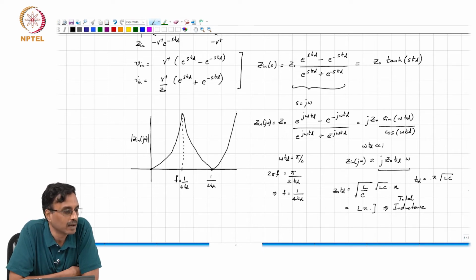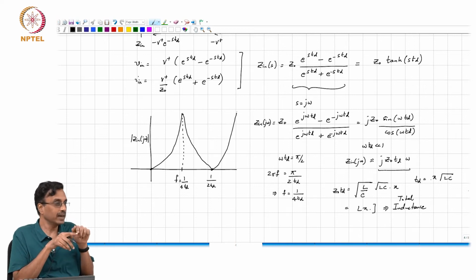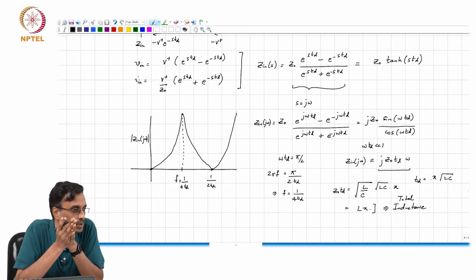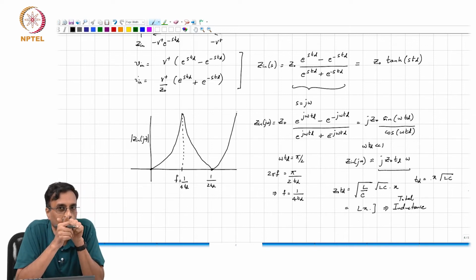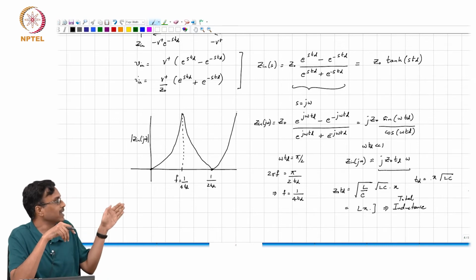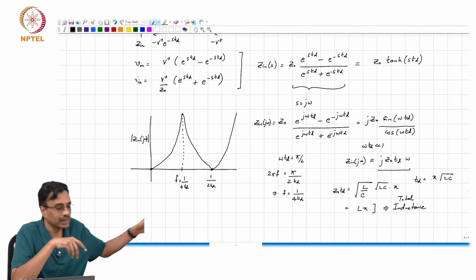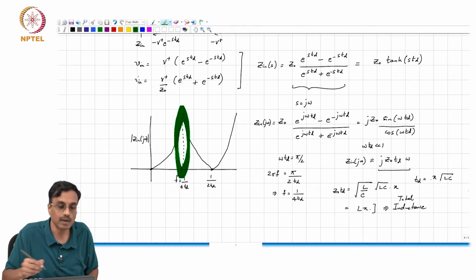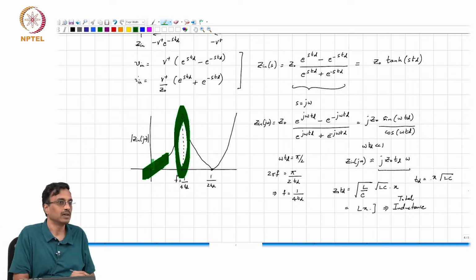All right. So, this whole notion of getting a short circuit is supposed to be zero impedance at all frequencies. Like most things in a textbook, it doesn't exist, because the moment you put two conductors with some finite length, the best you can do is, as you keep making the length shorter and shorter, what will happen? Well, the frequency at which this happens becomes higher and higher, but you can't escape from that slope.